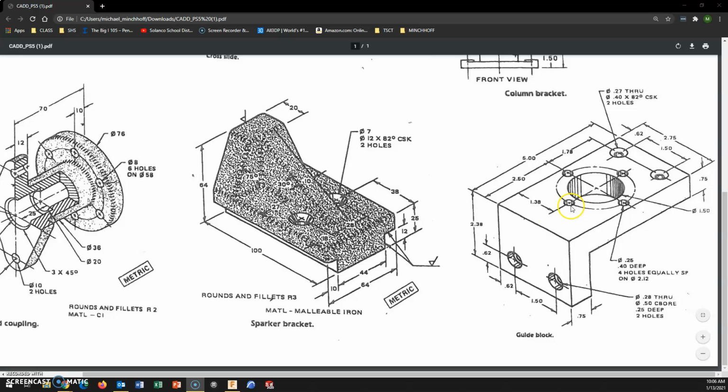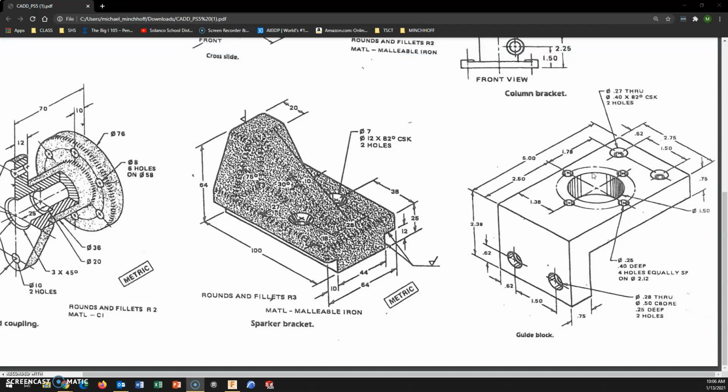For the flange coupling, we looked at doing it with the sketch. Here, since this is a feature that we have to create, we can then run that feature. It's going to ask us for an axis. Well, in this case, you technically don't have the axis that you want. What you do have is this larger diameter hole to reference. If I have a circle, it will reference that. This is how we're going to do it here.